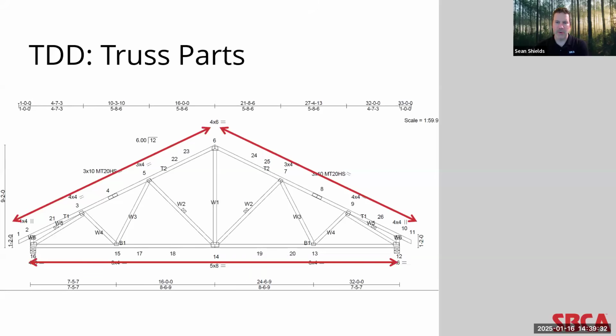Along the top of the top chord is the upper perimeter of the truss. This is typically where sheathing or purlins are applied in the field, creating the roof diaphragm. And the bottom of the bottom chord is in turn the lower perimeter of the truss. And this is typically where gypsum would be applied, or what is typically referred to as the ceiling diaphragm.